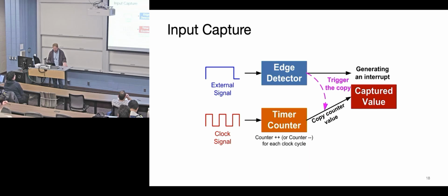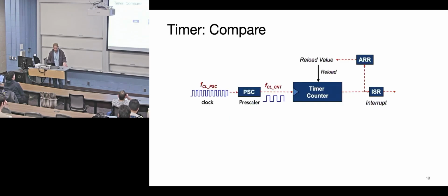I think this slide essentially does the same thing. Yeah, okay. The counter example is the compare register. When do you use a capture register versus a compare register? Or compare mode versus capture mode? You use a capture register to measure the time between 2 events, and you use a compare register to have events that happen at set intervals. Yeah, that's a great way of saying it.